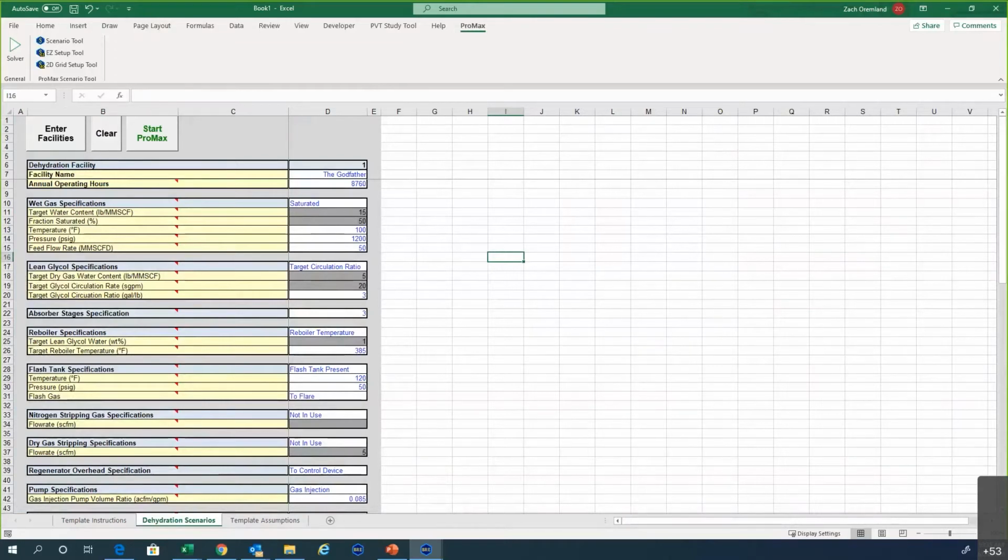That's a good question. So Steve asked, is the Peng-Robinson Polar package a customized package that BR&E has created from the standard Peng-Robinson package? Yes, it is a customized package. It uses Peng-Robinson as a base, and from my understanding, a lot of it has been data that we've collected from customers that have been willing to share their information with us, and we've input better fittings for how methanol interacts with hydrocarbons and water. But yes, it is a customized package. It's not something that comes just directly from literature. It's data fitted as well.